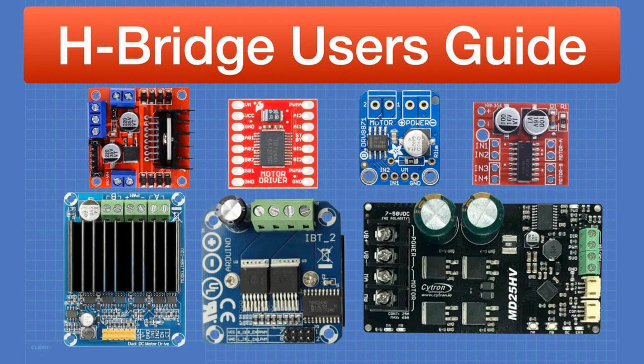6. Advantages of using VFDs. Improved energy efficiency. VFDs reduce energy consumption by adjusting the motor speed to meet the exact needs of the load. Reduced wear and tear. By controlling acceleration and deceleration rates, VFDs help to extend the life of motors and mechanical components. Enhanced process control. VFDs provide precise control of motor speed, allowing processes to operate at their optimal conditions. Reduced noise and vibration. Smooth acceleration and deceleration help minimize motor noise and mechanical vibrations.